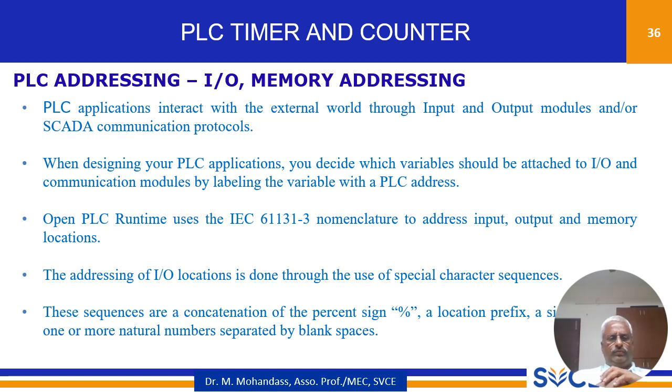For those functions we need to give the address, the way or the locations where the particular data are stored. PLC applications interact with the external world through the input and output modules and our SCADA systems. When designing your PLC applications, you decide which variable should be attached to the input output modules and communication modules by labeling the variable with the PLC address.